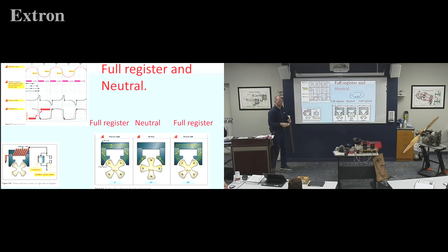With a four-pole rotor, with one rotation I get four events, but we're not going to get too far off into the weeds on that until after I explain it. But make sure you know the difference between two-pole rotors and four-pole, and realize that most of the magnetos we're dealing with, the slicks especially, are just two-pole magnetos. So we're going to have this magnet in here that's spinning around. It's driven by the engine. And actually, I'm going to draw it back up, north, south, so that's my rotor. We'll draw the housing.